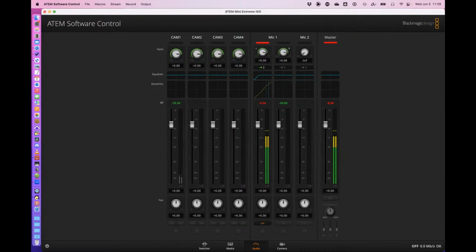So if you're coming in from embedded audio, the assumption is that the camera embedded audio is already correct. You've embedded audio in the camera, or you're using your audio mixer and you're dealing with that elsewhere. So some encoders, encoding for streaming, will have the ability to adjust delay between the analog audio and the video inputs, but the encoder built into the ATEM Mini series does not.